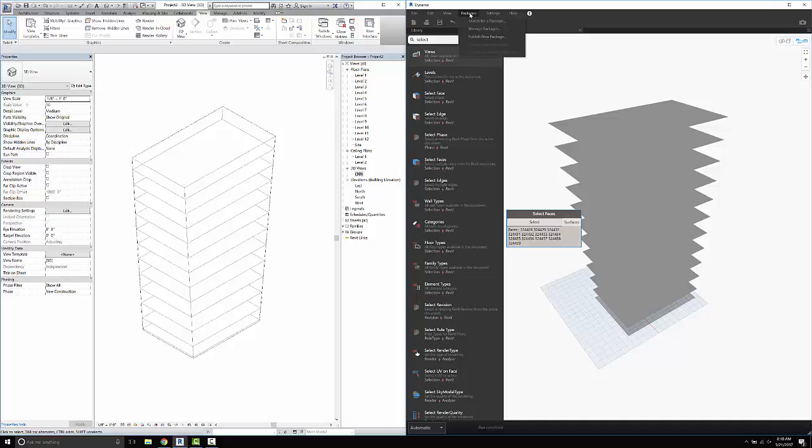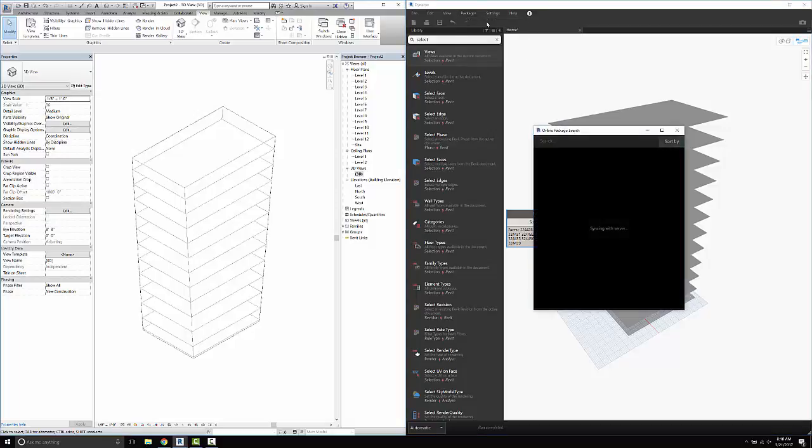And if you hit that tab, you'll see that you can search for packages. These are basically plugins that you can add into the components, to create more components and increase the capabilities of Dynamo. I'm going to hit search for packages, and you can see that it syncs with the server offline to be able to add in components. And what I'm going to search for is Lunchbox.